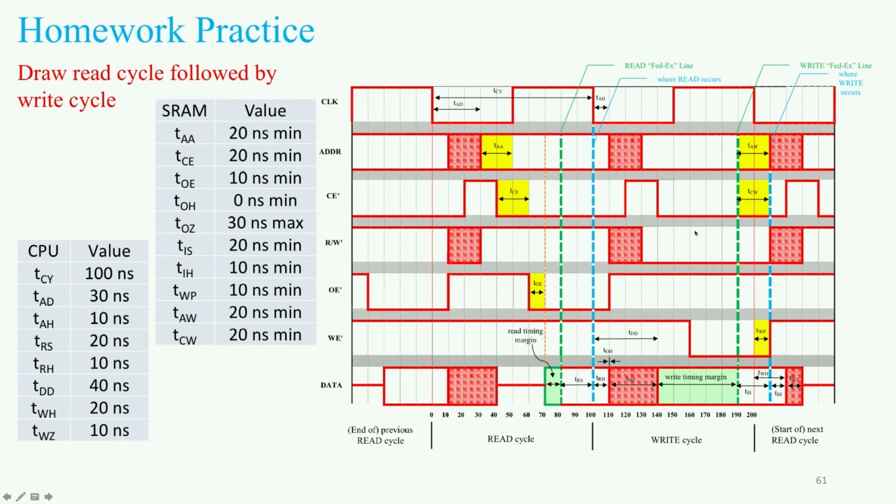So now let's look at what happens on the back half of this clock cycle. So that's sort of the front half, all of these signals up to this point. Now on the back half of this clock cycle, what initiates a change? So the clock goes high. Okay, fine. But remember, the SRAM doesn't actually have to output anything on the data bus now. Your data bus was already valid from the CPU. So the clock going high is going to initiate the SRAM read.